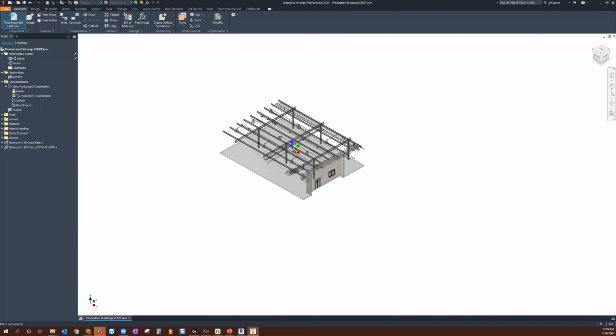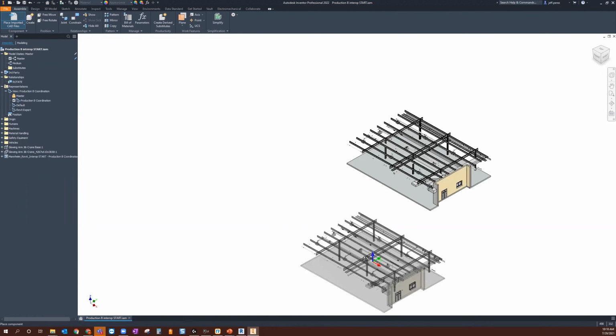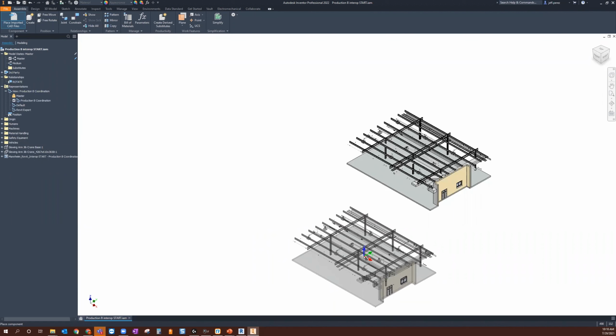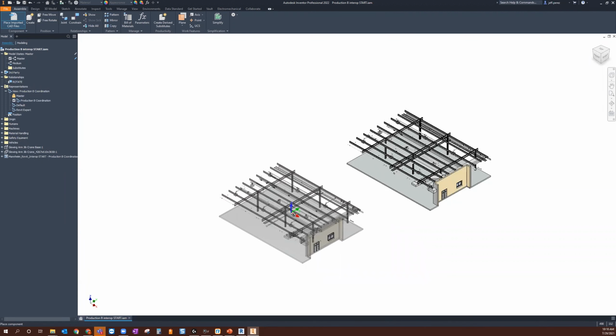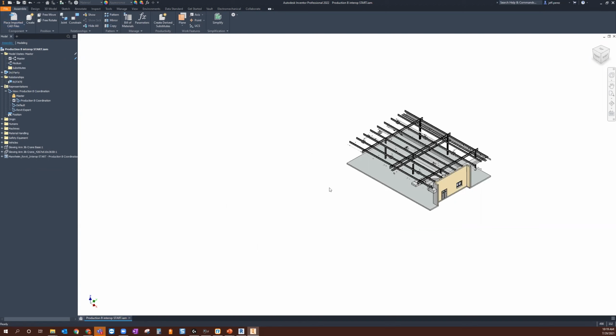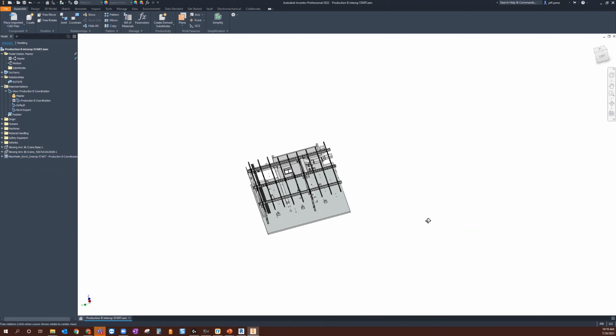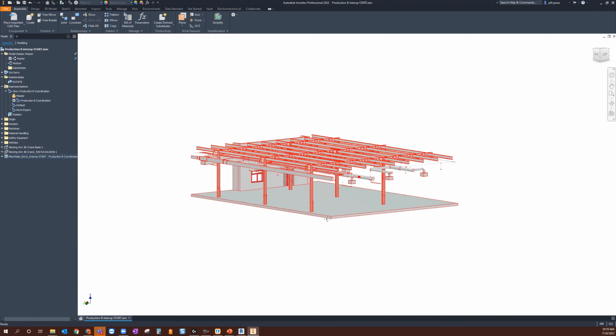Now, because we want to leverage the two coordinate systems together, we want our models to lay in the correct positioning. We're just going to place this model grounded at origin. So we're placing this specific instance grounded at origin to retain the origin locations, or the UCS system, between Inventor and Revit. Now that I'm happy with that being placed in here, I'll just click escape. Okay, so we can see that coordination view that I created inside of Revit brought into Inventor.